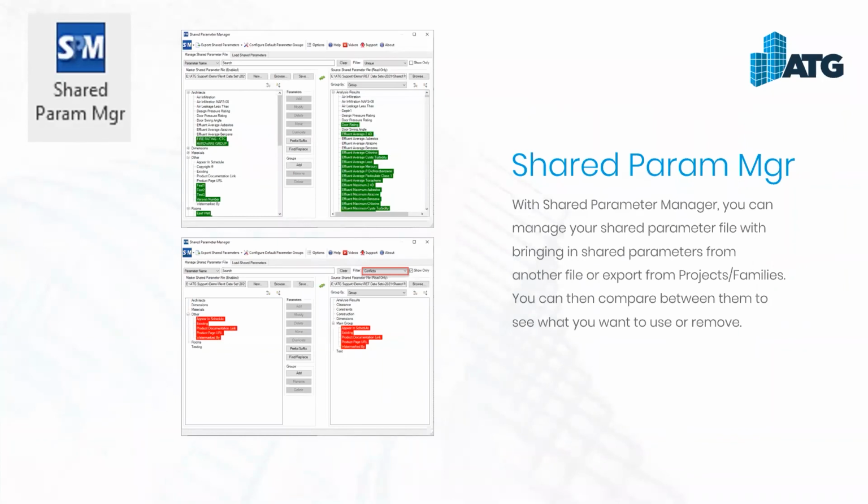So that is the Shared Parameter Manager tool. Again, it's a very powerful tool to go through and make those updates, so that you can modify the shared parameter file to then get ready to push the parameters to your family.